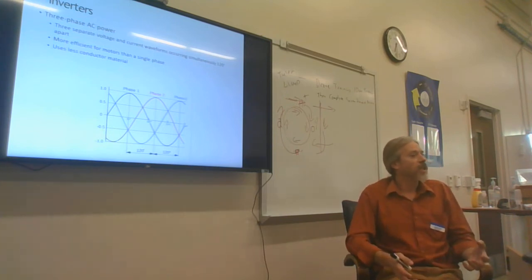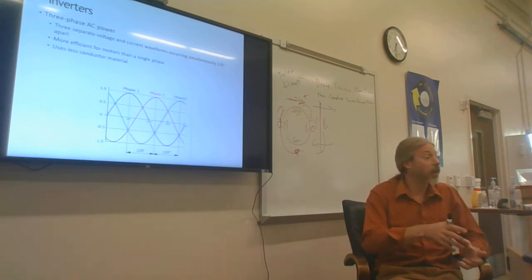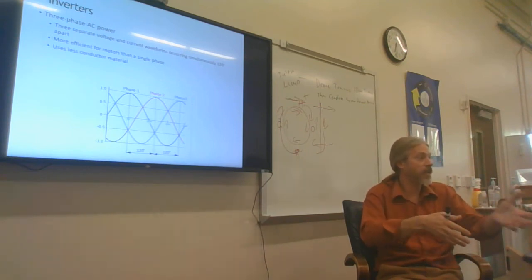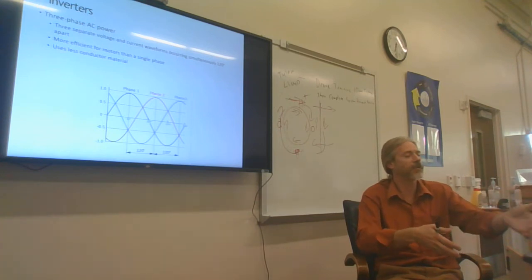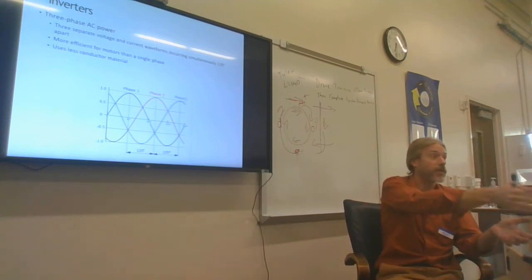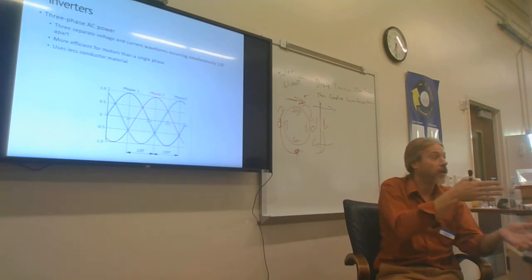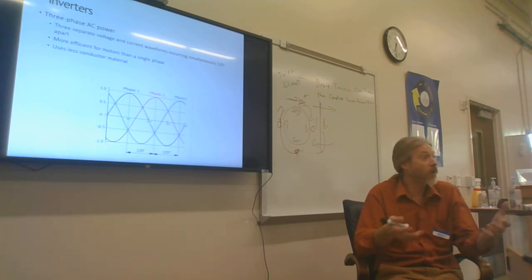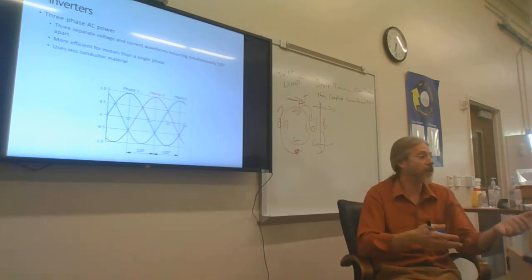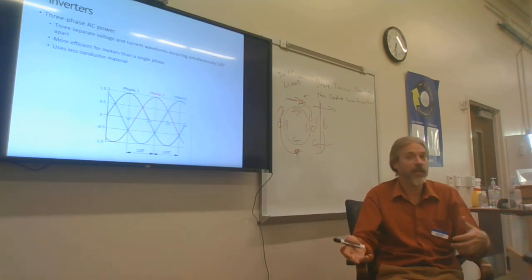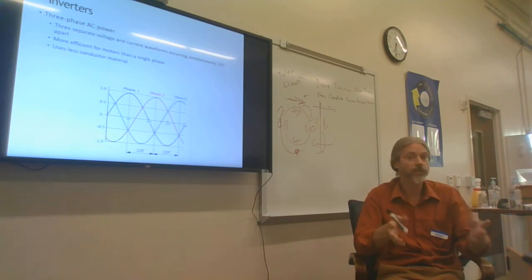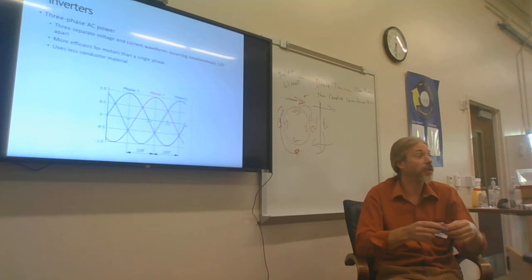But even then, a lot of times if they have single-phase power that comes to their house, they have a 3-phase converter that turns that single phase into 3-phase. You can't put a 3-phase inverter in for that customer if they have a single-phase grid connection. But in an event like Crowder, where we have 3-phase, it's smarter to buy either 3 single-phase inverters or 1 3-phase inverter. There are inverters that output 3-phase from 1 inverter. Those are cheap.